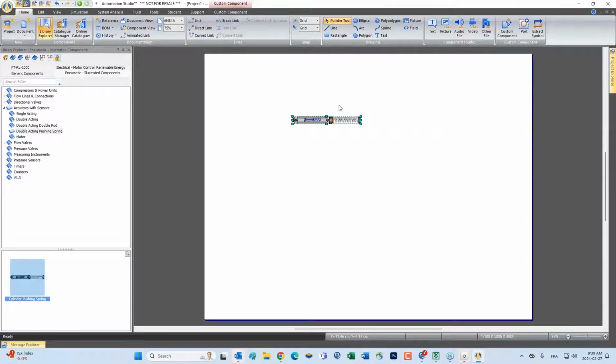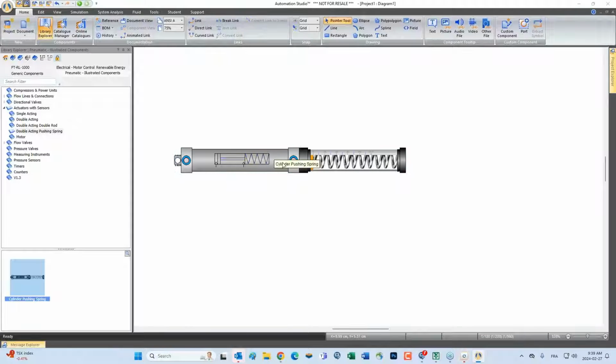Okay, so we can do things like that, but in this case, we also ask the customer to provide us with some readings when the cylinder is, let's say, 25% out, 50% out, 75% out. So we can adjust the resistive curve of that cylinder to reproduce the accurate reading.